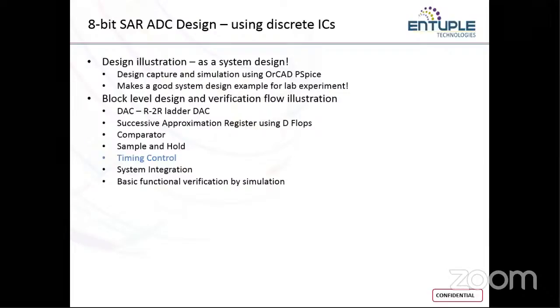So what we'll do is design and illustrate each and every block separately: your DAC, the R-2R ladder, the successive approximation register using D flops, the comparator, sample and hold, and finally we'll integrate all the blocks together and go for functional verification of the design by simulation.